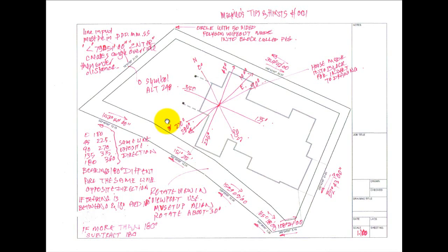Now the thing is that when you put them in, and you go and try and scale it, in this case here on our standard format, I've used a scale of 10 to 1, which is a 1 to 100 scale. You'll find that the lot doesn't fit on the paper, and that you have to rotate it in the viewport. So as you can see there, I've got north slightly rotated, that's where north is. So how do you rotate it? You rotate it in the viewport so that when you work on it in model space, it still stays true with its bearings and distances.